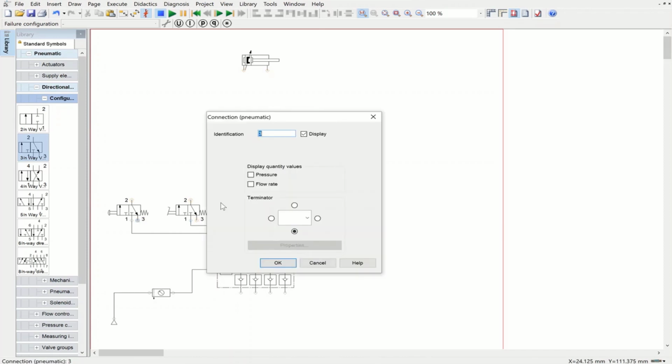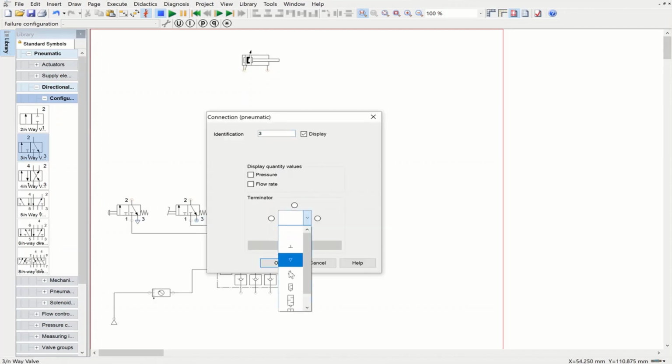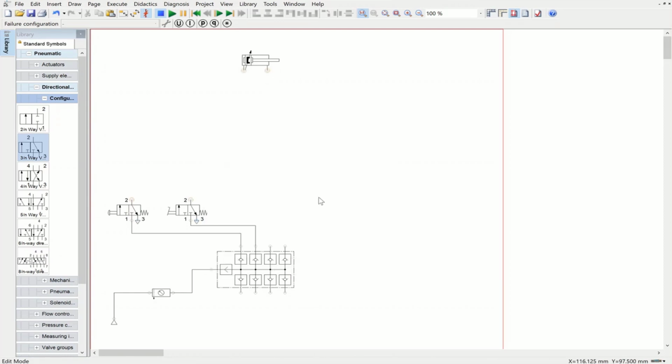and we need to have the exhaust, okay. So this is the exhaust needed. And then it is saying, or basically we can use push button or foot pedal, right, to start the cycle. So we need to have a shuttle valve.